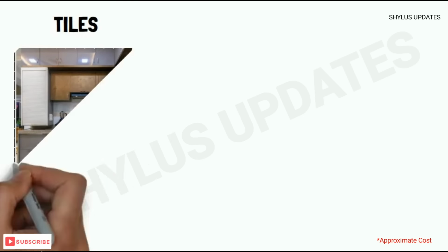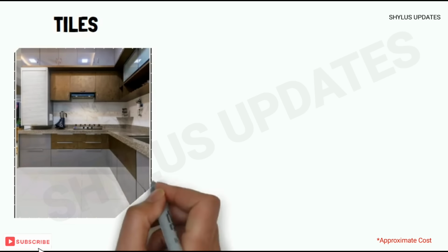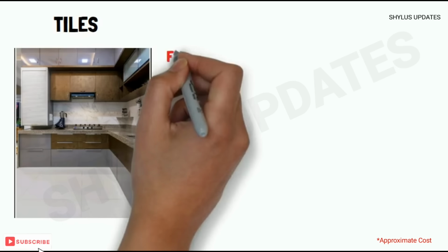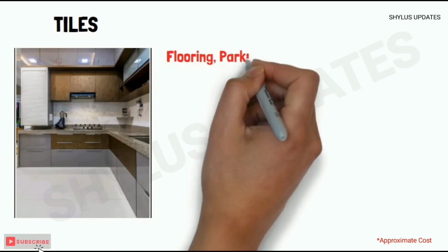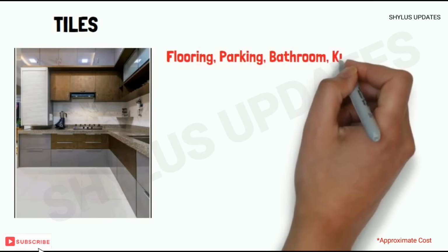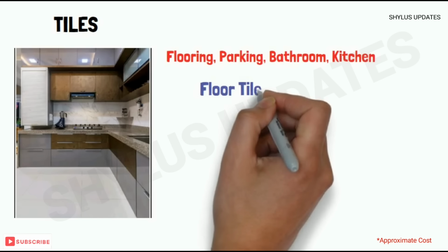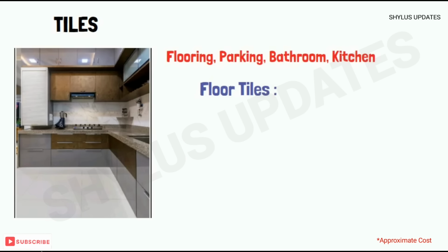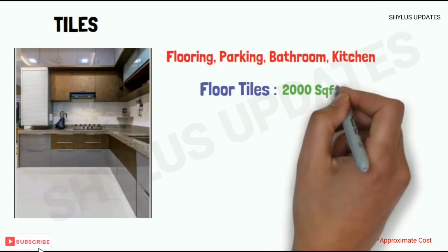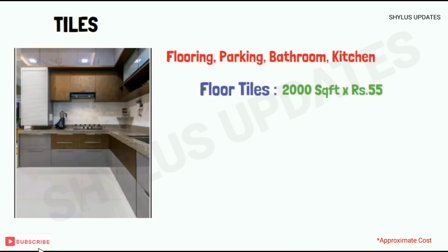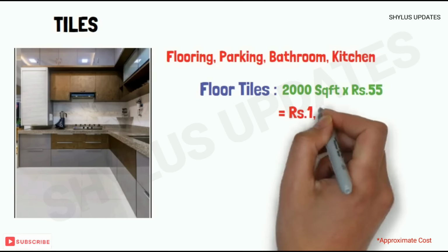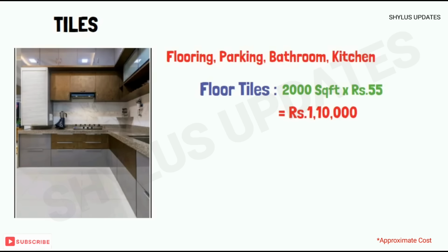Tiles. Tiles are used in flooring, parking area, bathroom, and in kitchen. Floor tiles are required for 2000 square feet. The current market rate of floor tile is rupees 55 per square feet. When you multiply 2000 square feet into rupees 55, you get rupees 1,10,000.